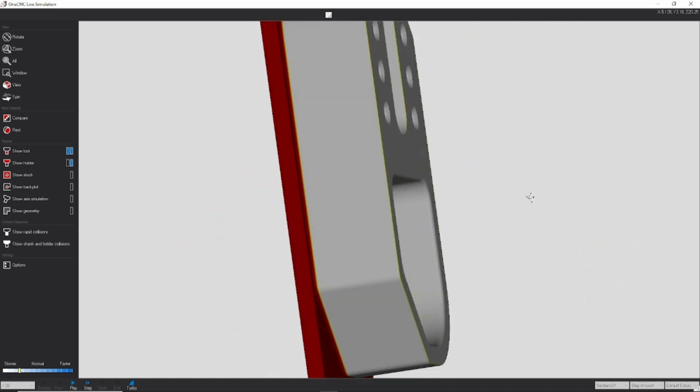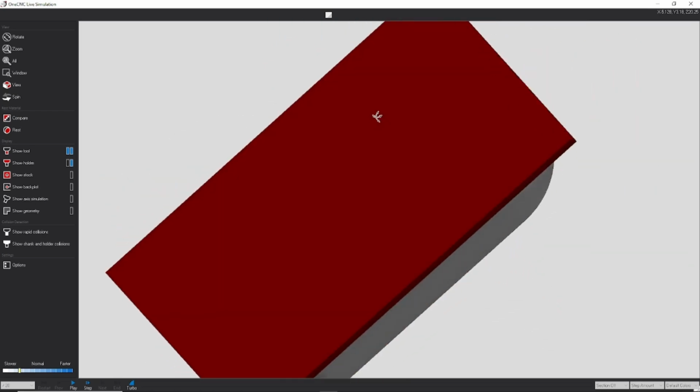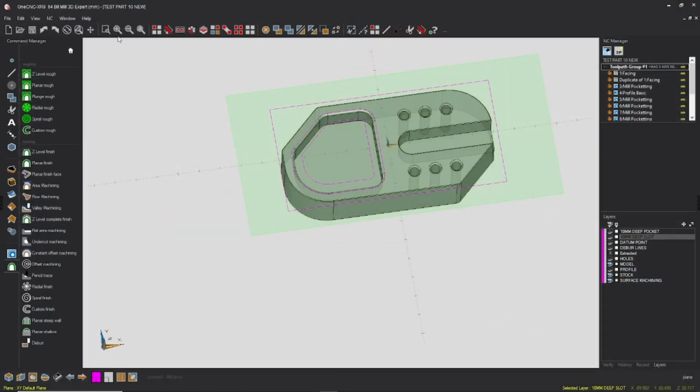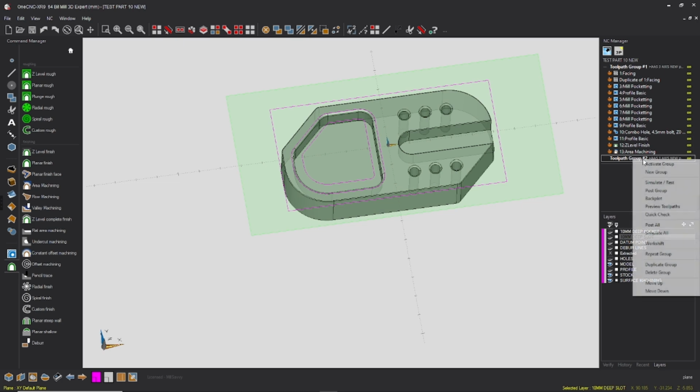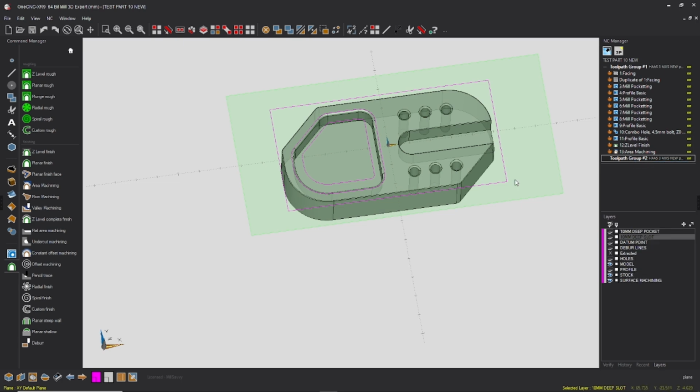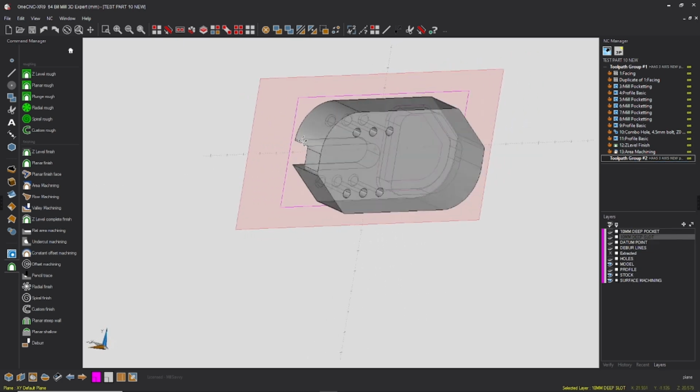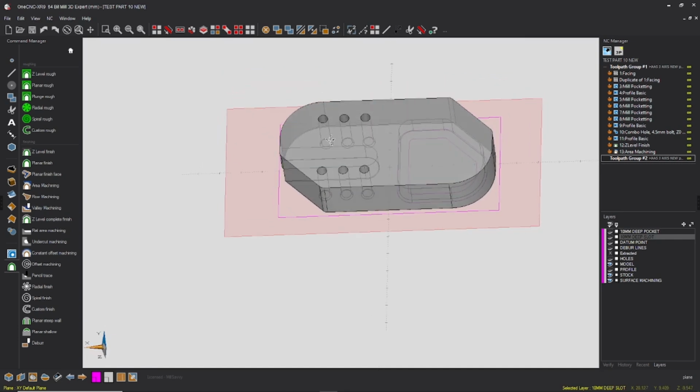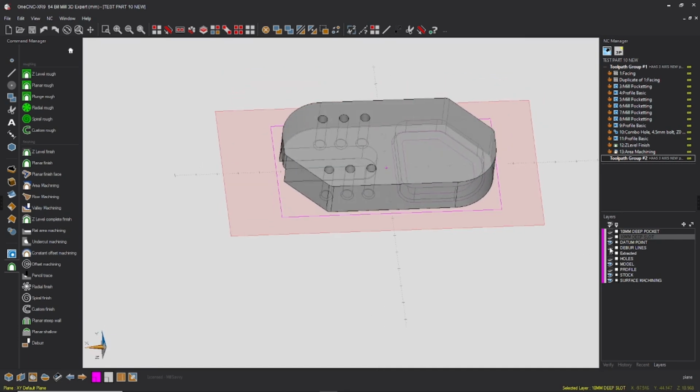So I can see, look, I've finished everything other than removing the back. So what we're going to do, we'll do that now. Let's click save. We'll move this down a little bit, create ourselves some space. We're going to create a new group, and then set that to our active group. And now we're going to create a plane on the back. I'm going to put that datum point on and turn everything else off.